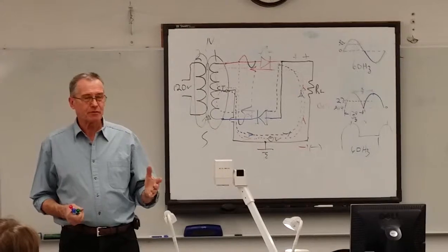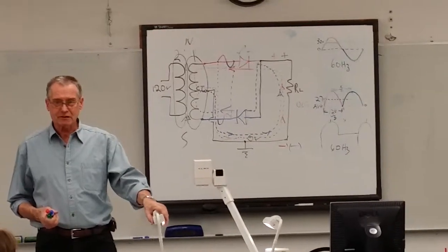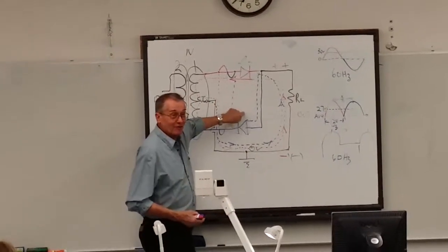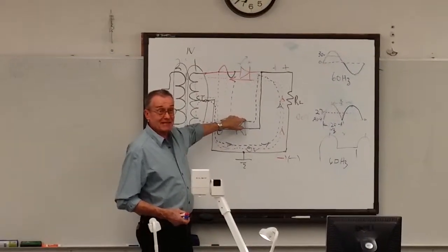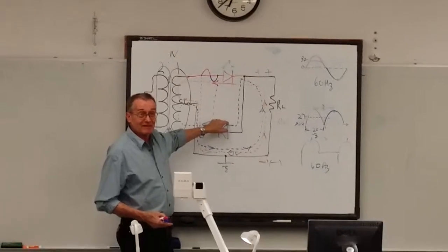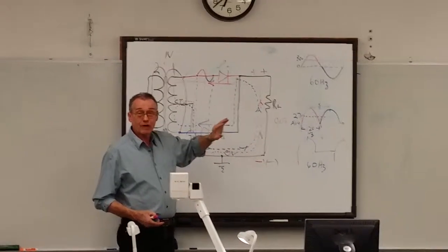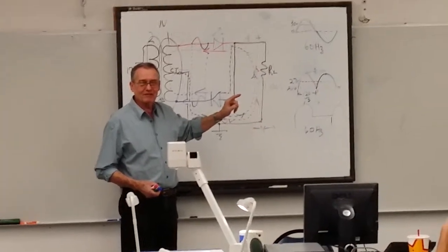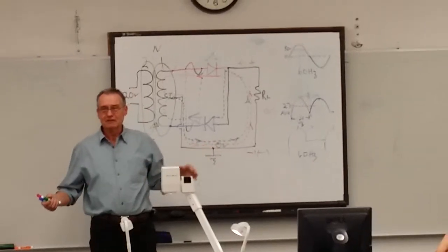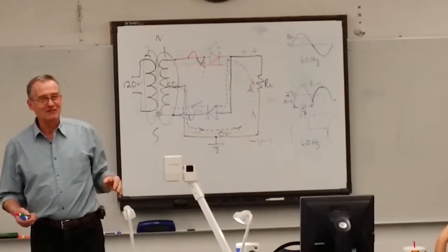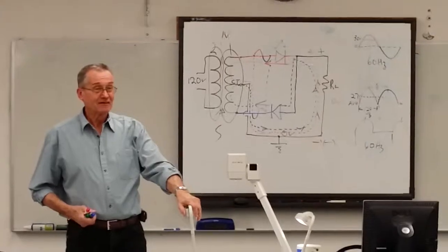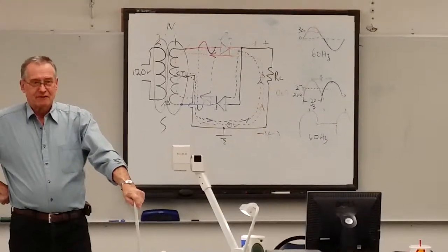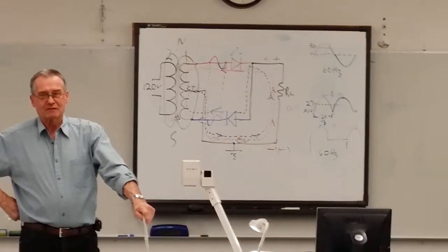So if you were a company making these things, you would say, I'm gonna add a second diode here that costs about 8 cents, compared to a $4 savings. Why not just spend 8 cents more and cut the capacitor in half, and now you've saved yourself about $3.92, if you just put one more diode in there. That's when the CEO earns his money.